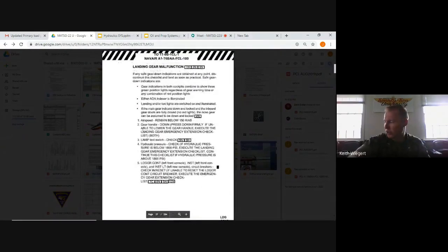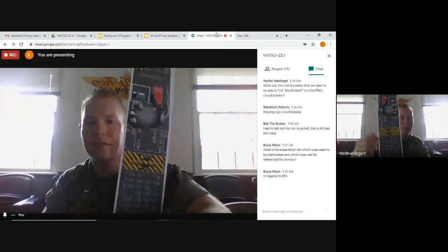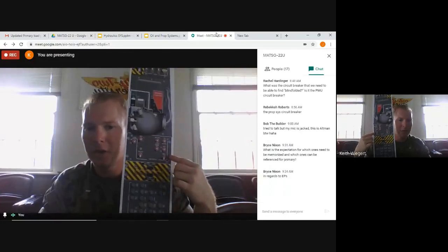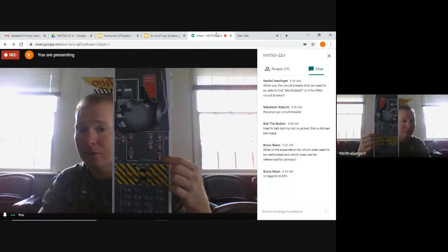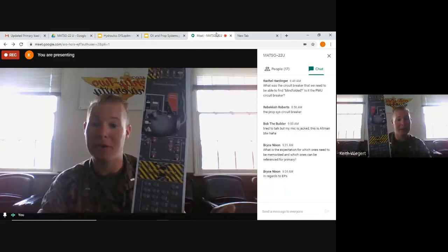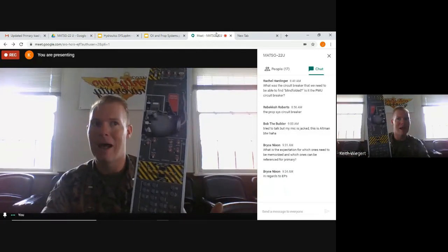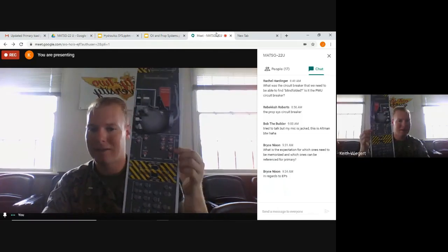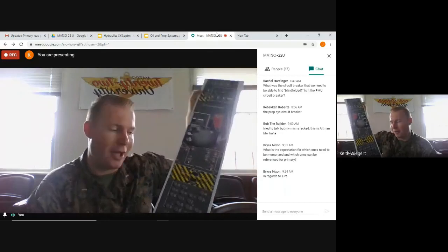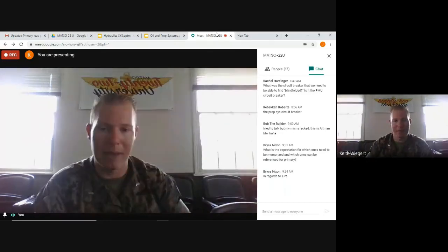So with that, in the cockpit, underneath your PCL, you've got basically the system test panel down here. You've got the lamp test switch, which is this one there. When you hit that lamp test switch, all it's going to do is turn on everything inside the cockpit that has a light bulb, right? So all your indications and stuff. It turns those on so that you can determine if your light bulbs are burnt out or not, right? So that's what that was about.